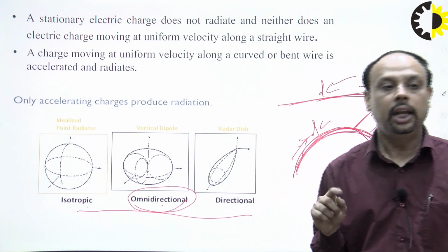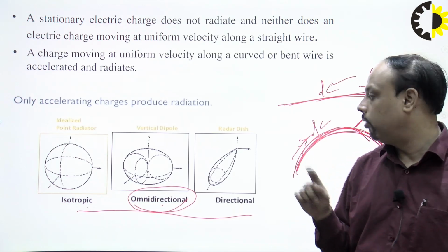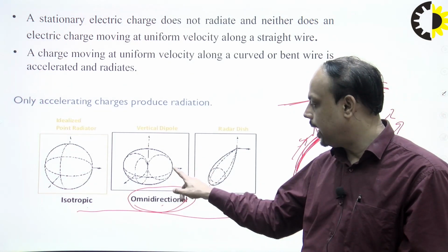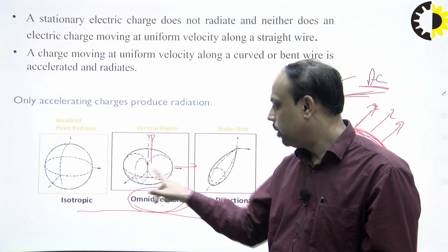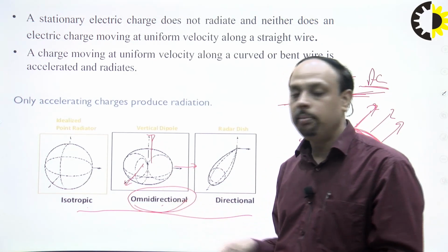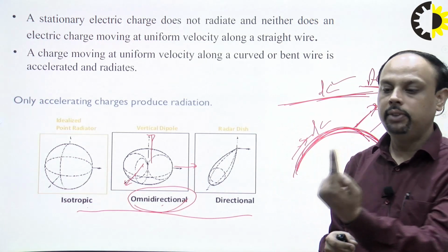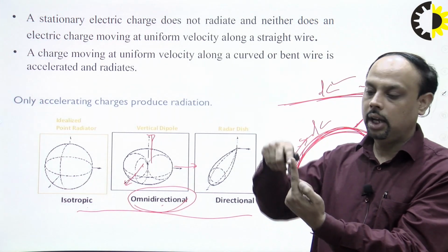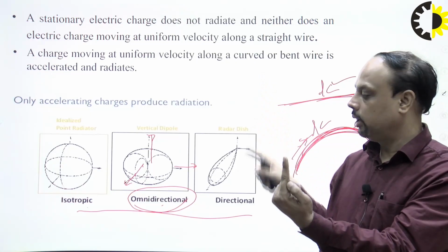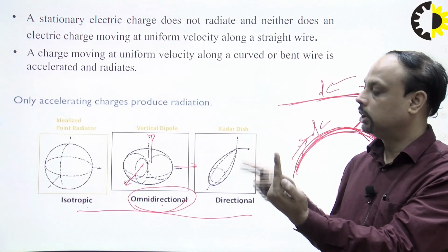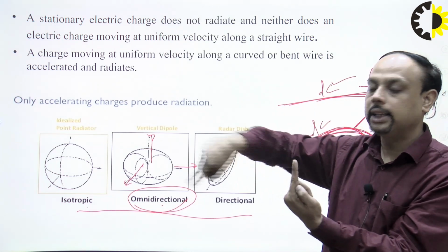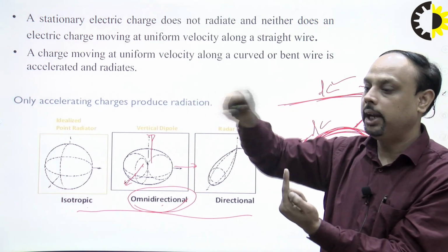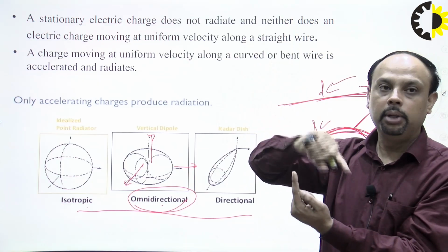While an omnidirectional antenna can radiate the same amount of power in one particular plane, like the xy plane, it is not uniform in the z-axis, but it is uniform in the xy plane. If there is a dipole antenna and it radiates, it forms a donut-type structure across the complete xy plane, but this radiation is not uniform in the z direction.